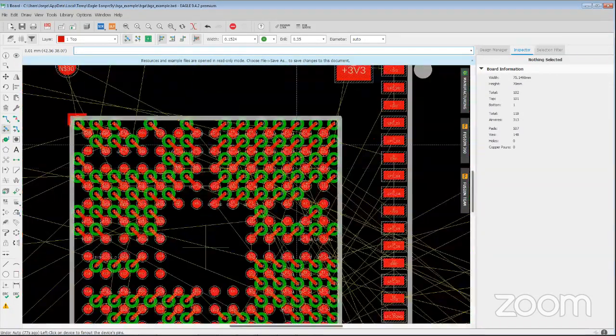So that will let you know, hey, I probably need to adjust my design rules or see if I can get smaller drills. So that makes it a useful feature, to for a moment allow violations and see why it wasn't able to fan out the component. So I'm going to go ahead and undo that.